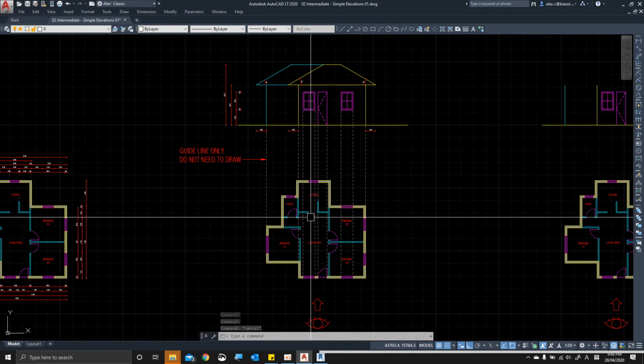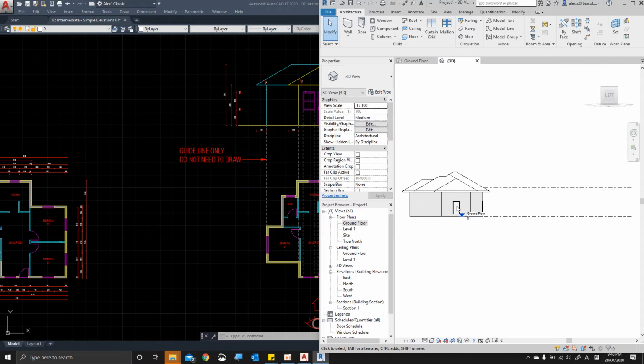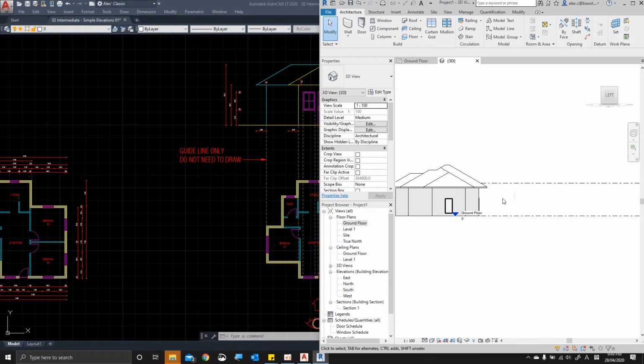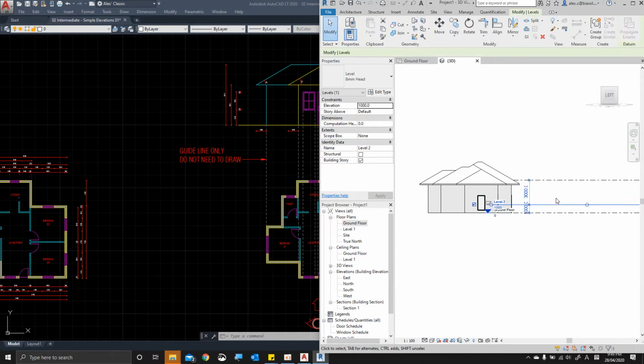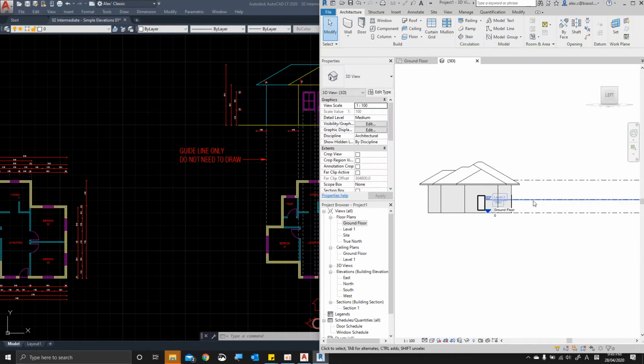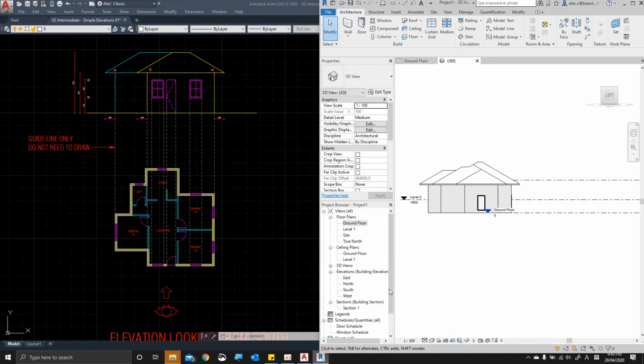That is because the plan is a representation of, if I see here, so that is the ground floor, but maybe if I draw a line here, the basic concept of the plan is you cut a line on that floor at about your eye level, so 1.7 meters high approximately, and look down from there.